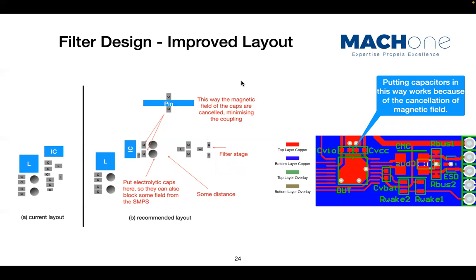Okay, so we found out the reason, but we can't really just say it, because this is a professional automotive PCB board design from big companies. You can't just say, oh, put a copper tape, right? So you have to give them really good EMC advice. So in this case, we advise them to basically re-layout the switch mode power supply filters.